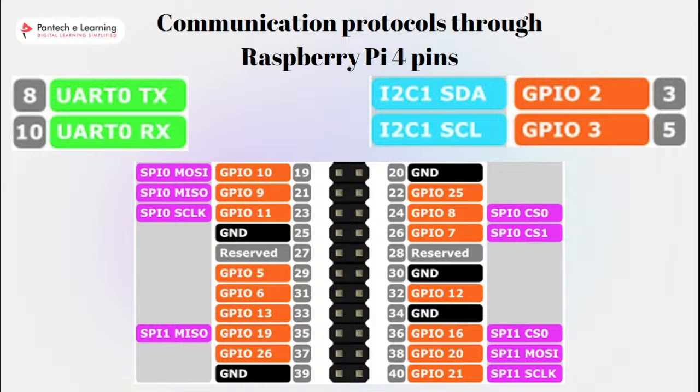Make sure you know which voltage is accepted by the component before you plug anything. But don't worry too much though. Usually hobby components will accept 3.3 volt and or 5 volt, right? Note that serial data and serial clock pins on the Raspberry Pi are alternate functions for GPIO2 and GPIO3. So when you use a library, Python or CPP, etc., for I2C, those 2 GPIOs will be configured so they can use their alternate function, right? Some of the best and easy to use libraries for I2C are listed here.